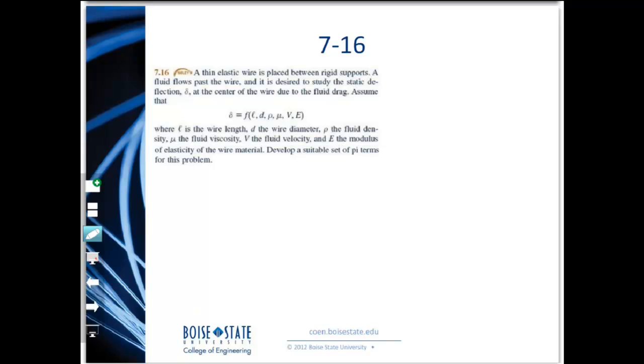Assume that delta is a function of L, which is wire length, D, the wire diameter, rho, the fluid density, and mu, the fluid viscosity, and V is the fluid velocity, and finally E is the modulus of elasticity of the wire material. So you're asked to develop a suitable set of pi terms for this problem.